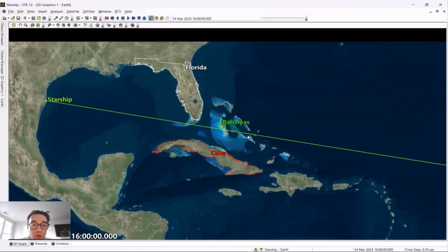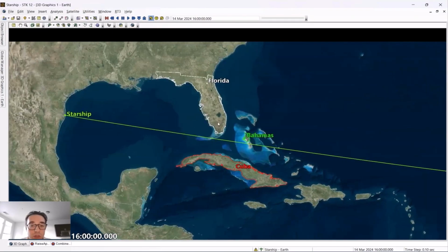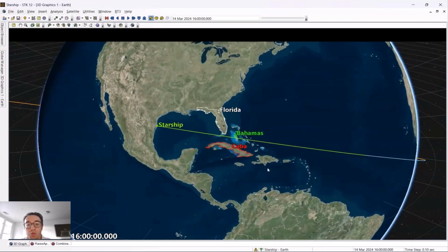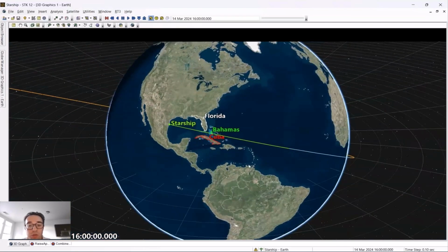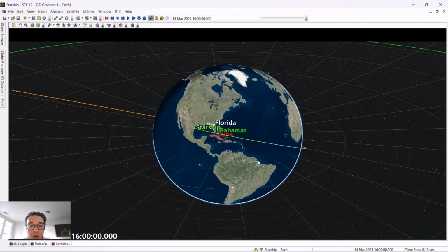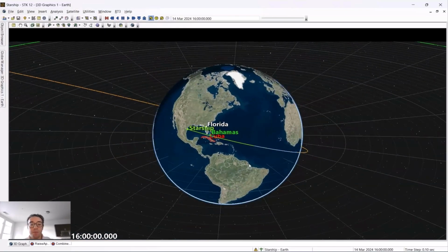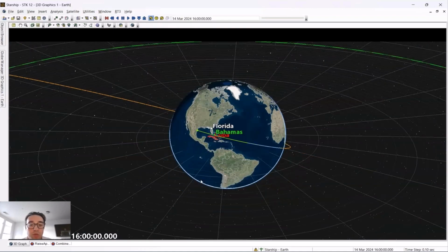These constraints were the minimum access durations with our airspaces that we don't want to violate with our launch. We also managed to define, thanks to the parametric study and the carpet plot, which input variables are the most detrimental to our study. And we managed to see that the azimuth at burnout is the most detrimental one.